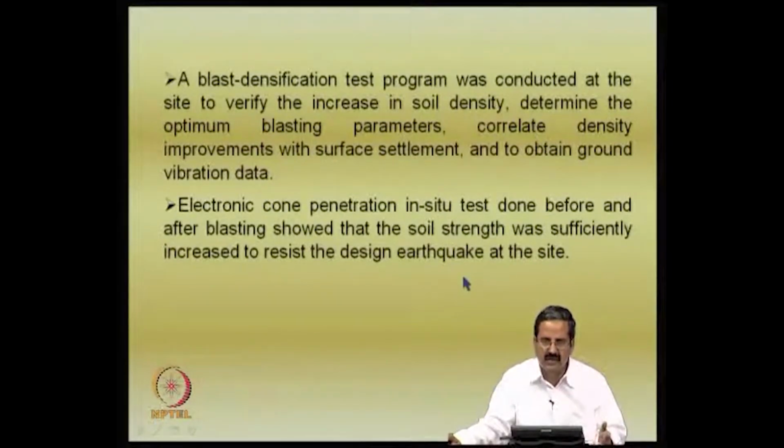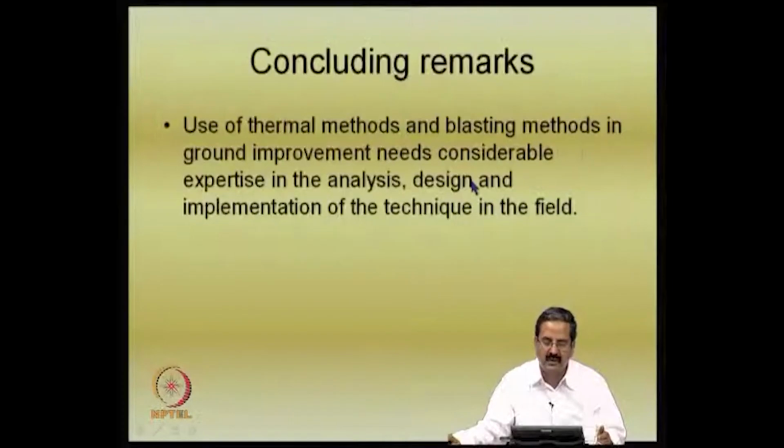Once they were able to achieve this, they were also able to confirm it with field observations from CPT tests, and they had enough soil data to confirm that their design is correct, and finally they were successful in conducting the blast densification program. And as I just mentioned, it has been quite cost effective compared even to the standard dynamic compaction methods and other methods of ground improvement.